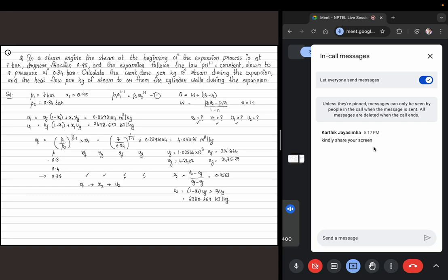I have P1, V1, P2, V2, and U1 and U2. So I have all the variables that I require. So our work done is straightforward. We just substitute this in the formula. So we have P2 V2 minus P1 V1 by 1 minus n, where I'm just converting it to appropriate units. Just multiply with 100, we'll do it in the last. That is just to convert it to kilojoule per kg. And we have the final volume to be 4.05526.